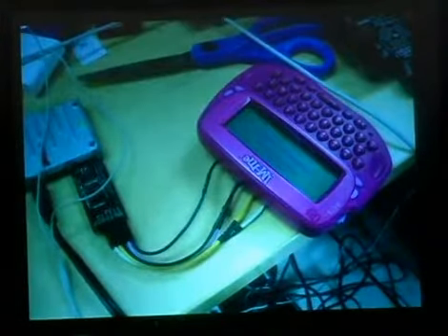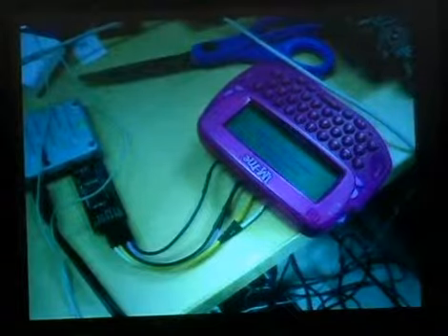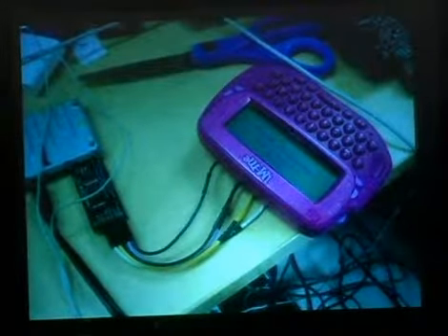Instead, they have these test points beneath the battery compartment. You'll see these in almost every cell phone. These also exist in the Turning Point clicker. You can wire these up using just little jumper wires, run them into a GoodFET. Here it is. And then you can reflash it to be anything.